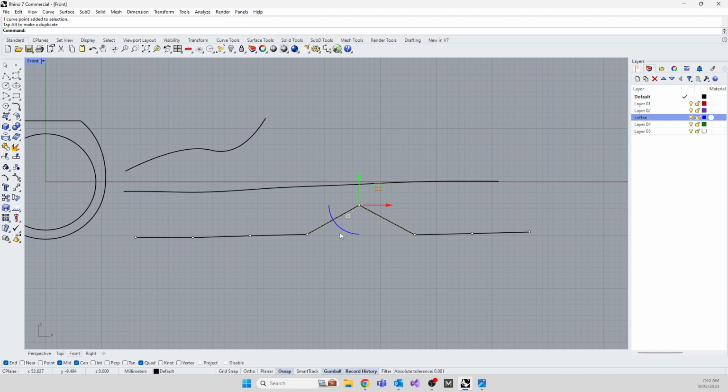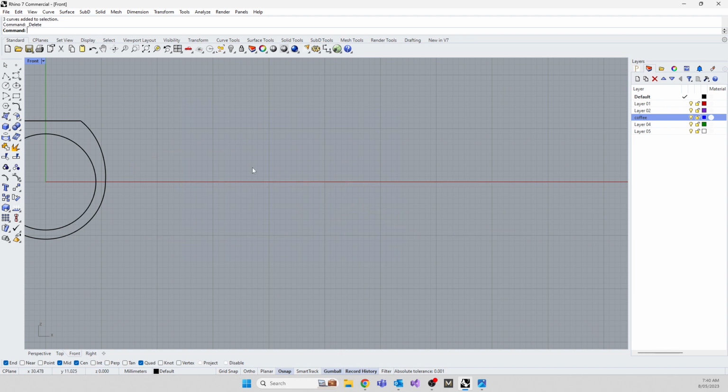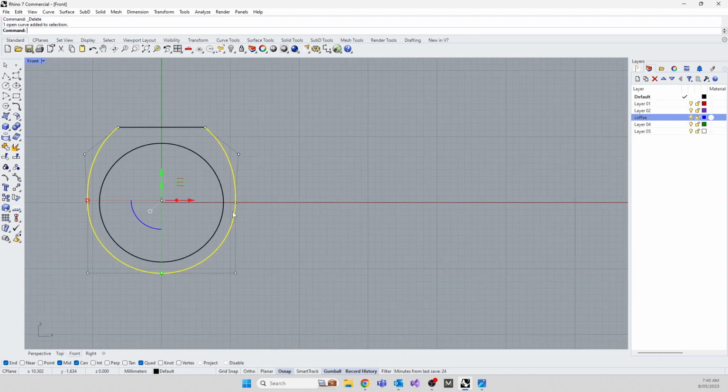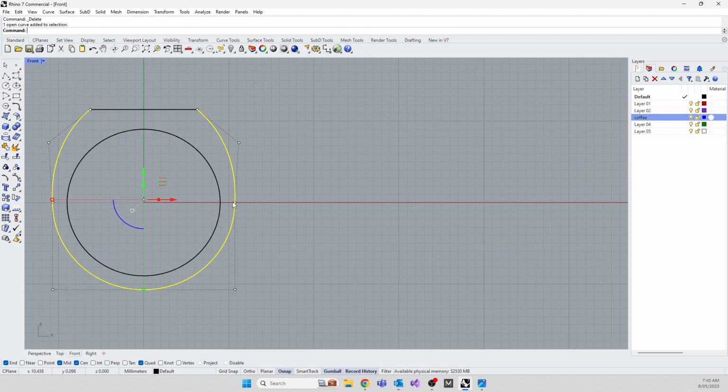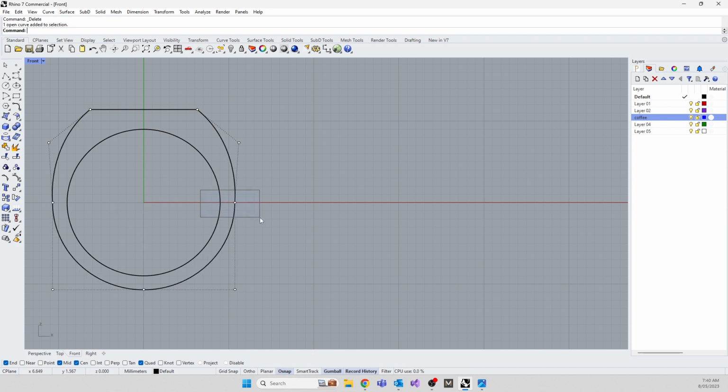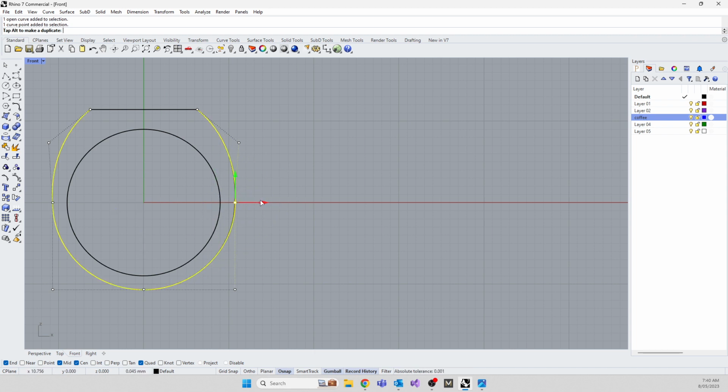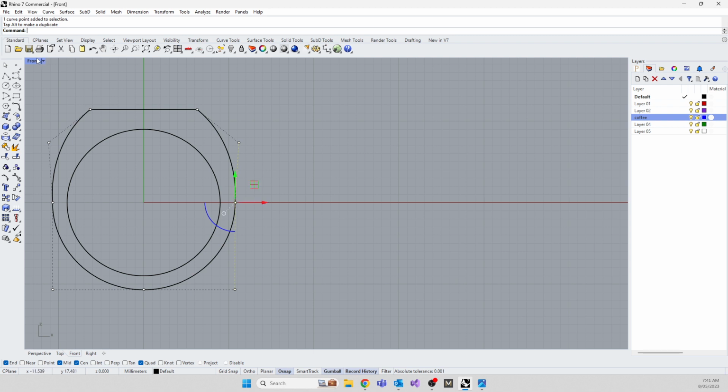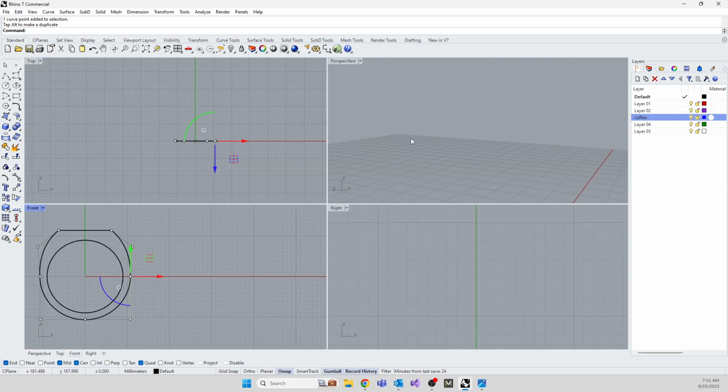We'll get to this in a more advanced lesson. Let's finish up this one for today. All right, so anyway, because this was created as a series of degree 2 curves with a kink inside there, which is degree 1, I need to get rid of this nonsense, because when I extrude, you'll see what happens, you actually get different surfaces. I don't want different surfaces, I want one surface.